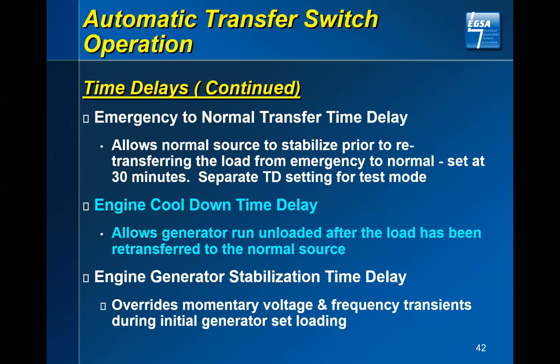The engine cool down timer: you've run this engine for a period of time, an hour or more. We do this with our car. We simply pull into the driveway and shut the car off. In the case of a generator set, you're going to unload that generator, and typically it will run for about 5 minutes unloaded to cool itself down. A point to make on that is I've had calls from technicians that say I've transferred back, but my generator is still running. You have to look to see if there's a 5-minute timer in your generator controller and a 5-minute timer in the transfer switch. You may want to zero one of those out.